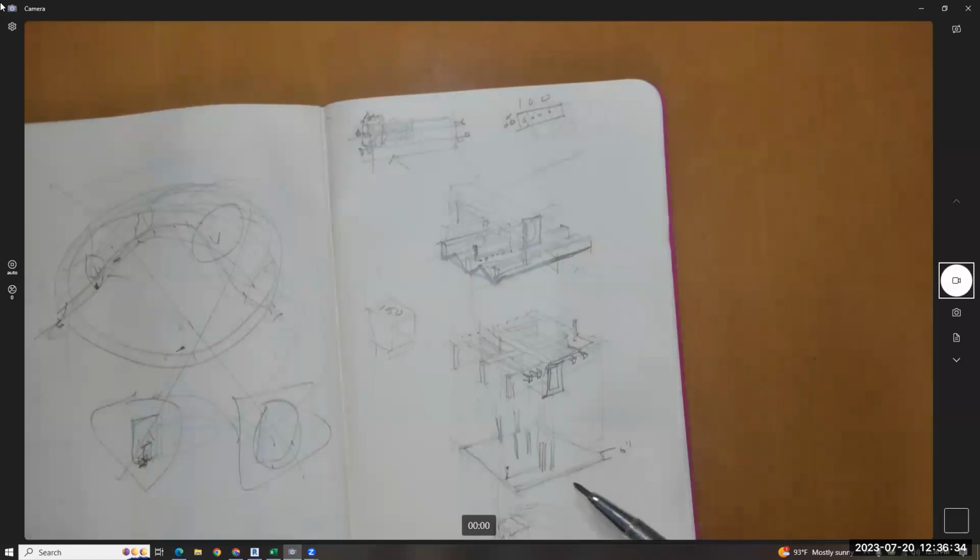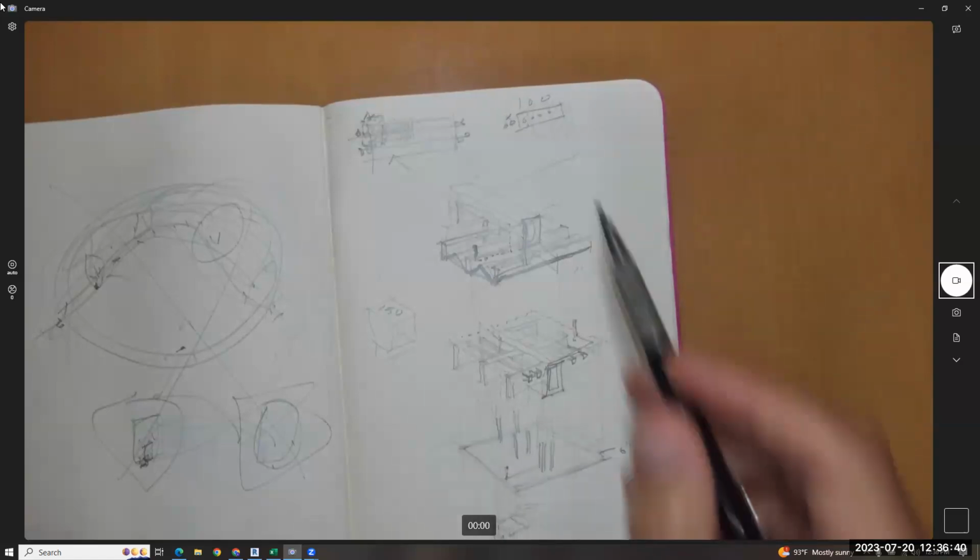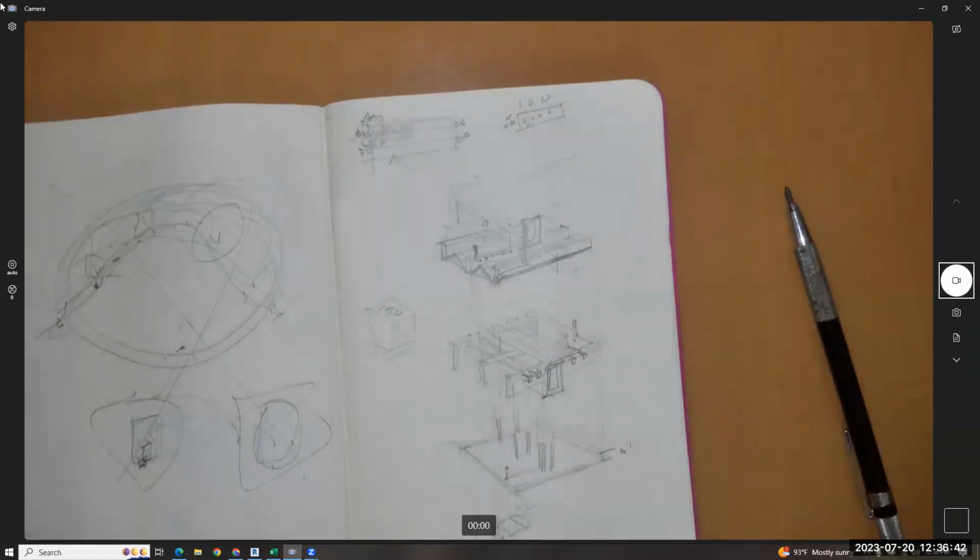Okay, so what is the weight? If the trib area for this column is 6,000 square feet and it's 6 inches thick, what's the weight of that floor? Do it in your head. There's one multiplication. The rest is logic.